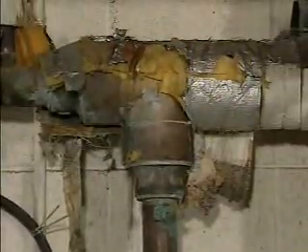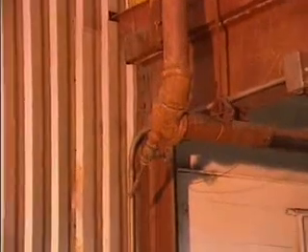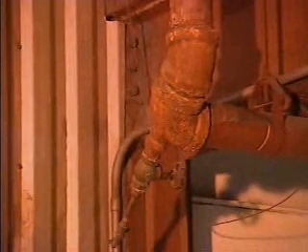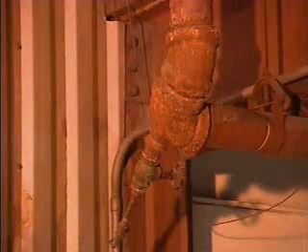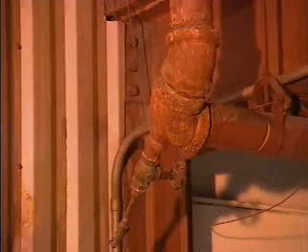Inspections involve examining pipes and pipe fittings for wear and damage. One of the most common types of damage to pipes is corrosion. Corrosion is the dissolving or wearing away of metal. Corrosion can be either external or internal. External corrosion occurs when a condensation of moisture from the air or another source forms on the outside of a pipe. This makes the pipe appear to sweat.